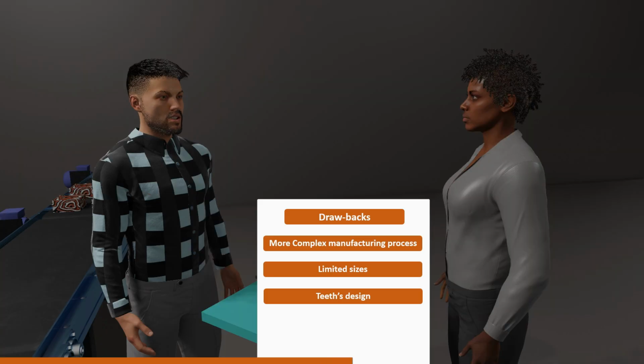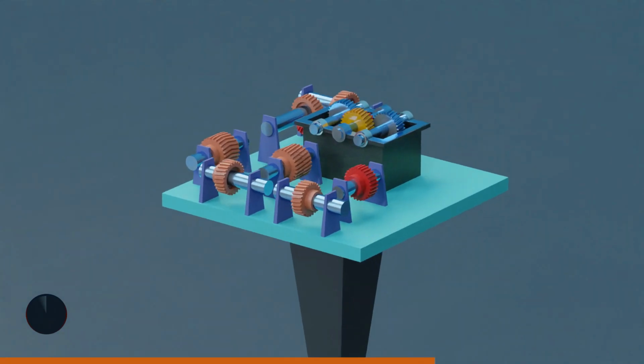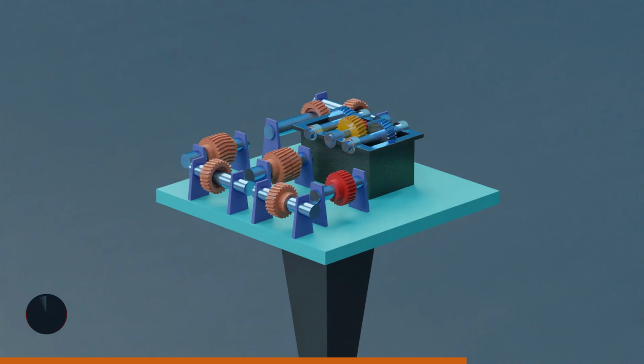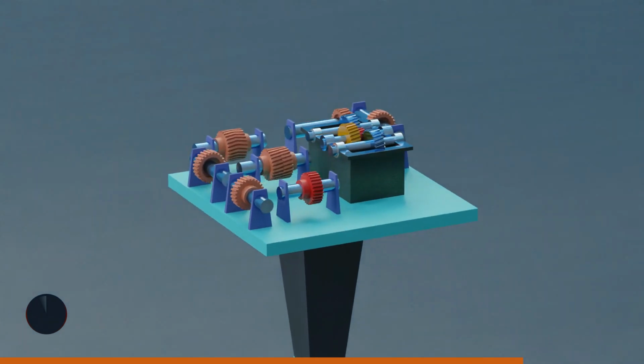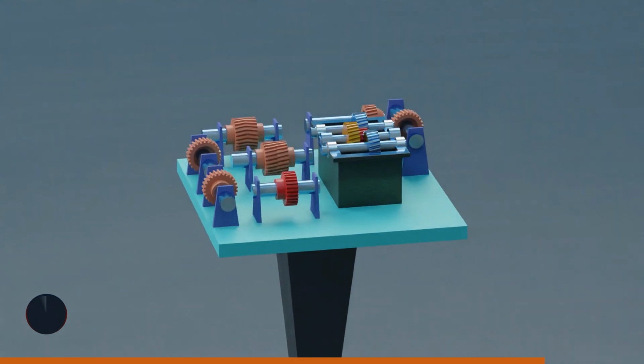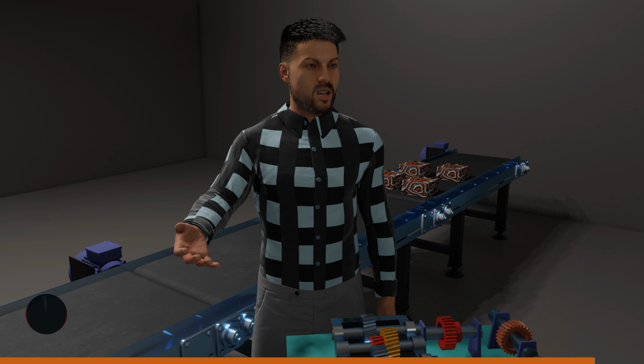The inclined teeth on helical gears tend to generate a high axial thrust force, which the bearings and other components in the system must accommodate. So there is a need to use special bearings or other components to support the gear sets. This will in turn add to the cost and complexity of the system.